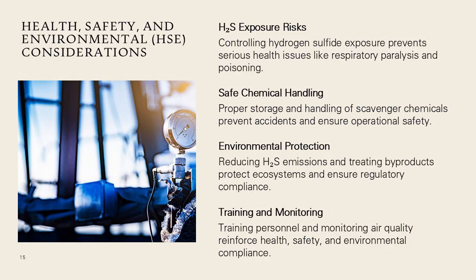H₂S scavenger programs contribute significantly to improving health, safety, and environmental performance in oil and gas operations. Controlling H₂S reduces risks of worker exposure, which can lead to respiratory paralysis, eye irritation, or fatal poisoning at high concentrations. Safe handling of scavenger chemicals is equally important, as some formulations may be reactive or require specific storage and injection procedures. Environmentally, lowering H₂S emissions supports regulatory compliance and reduces the potential for atmospheric sulfur deposition.